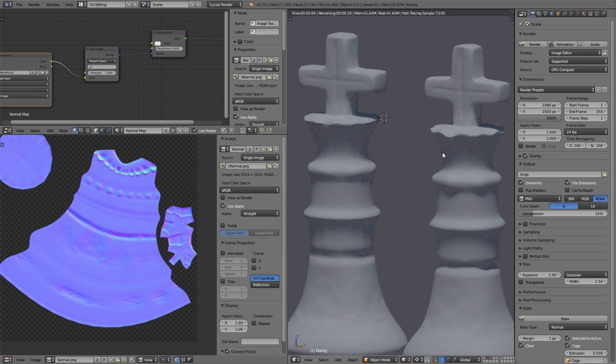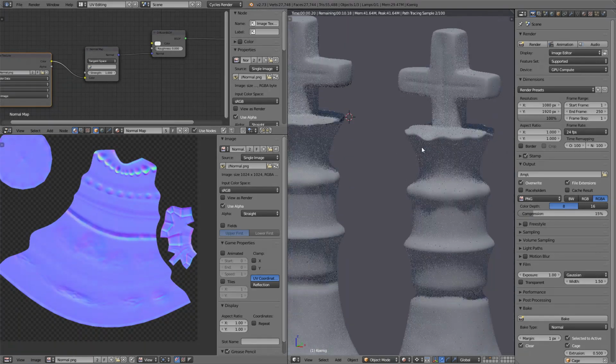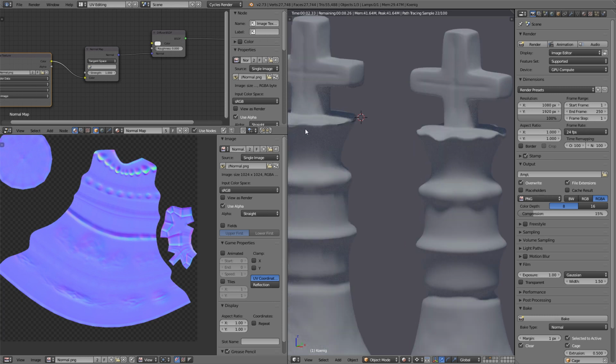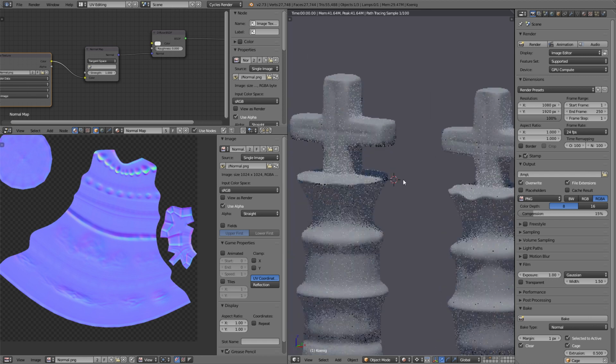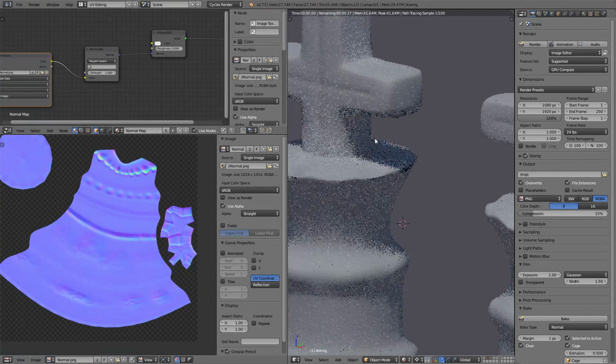They don't cast shadows, so we don't see the wave in the shadow as we see with a high poly object here. And of course, the biggest shortcoming would be over here, but that's impossible to be displayed by a normal because this is below the surface of the object here, and this one is above, so it can't poke through to both ends. This is a pretty extreme situation, which also explains why we have the very bright green colors over here, where Cycles tried to, well, do the best it could to solve this basically impossible combination.